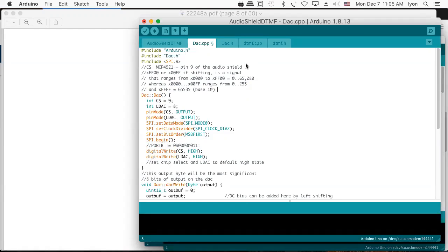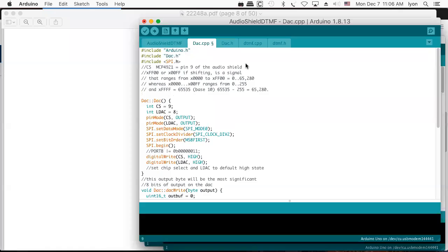Sorry. So if you make the least significant 2 nibbles equal to 0, then what you're doing is subtracting 255 off. So 65,535 minus 255 gives you 65,280. So you're expecting a different range if you're working with the most significant 16 bits. But then somebody says, but wait, it's a 12-bit DAC. So if it's a 12-bit DAC, where are we?